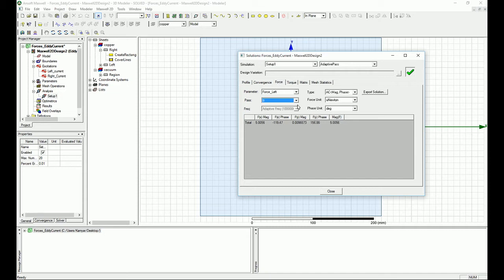And when you go to the higher number of passes, you can see the changes are insignificant. Okay, so this is good news. When you are doing EM simulations based on the engine that they have, most of the time it's a good thing to check how it reacts between the different passes. You want to see something like that.